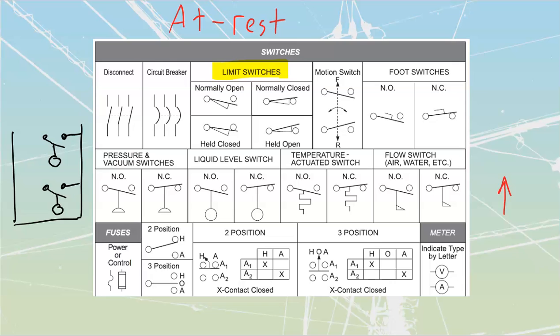Okay, so I've got 2 float switches inside of this pit. Let's start filling this pit with water. Bloop, bloop, bloop, bloop. Just like that. We see that this float switch, as we increase the water level, that float is going to move in the upward direction. And eventually what happens is that our process variable, that's a fancy term for the thing that we are controlling. So over here, my process variable moves up to a point where it is going to go and permanently hold my switch. At this point, when this thing is underwater, it is a NO, normally open, held, closed, contact.